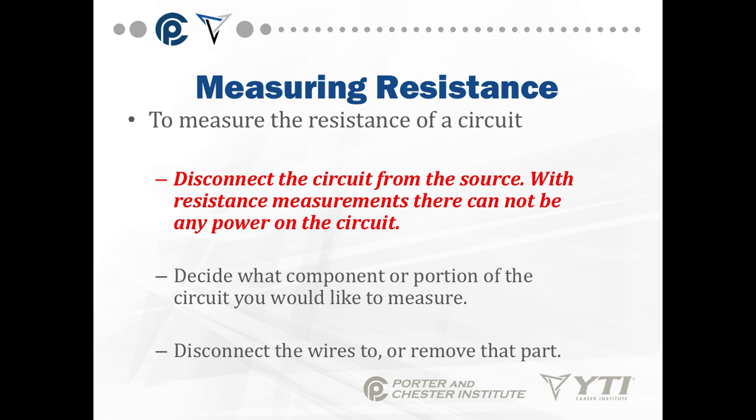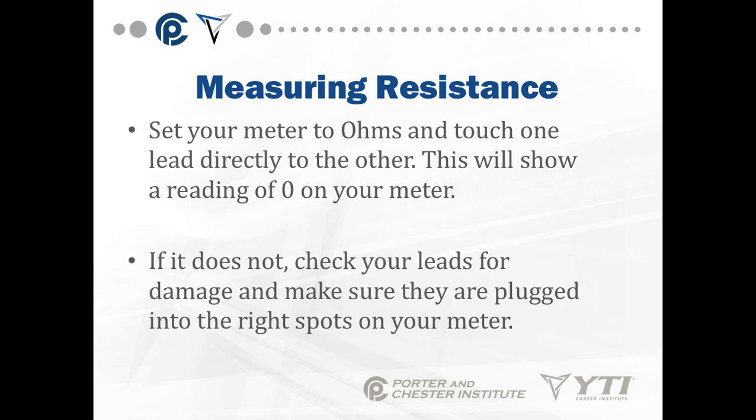To measure resistance of a circuit, you have to disconnect the circuit from the source. Do not ever measure resistance on a circuit that's plugged in or powered. You will burn your meter out. Decide what component or portion of the circuit you would like to measure. Disconnect a wire to or remove that part.